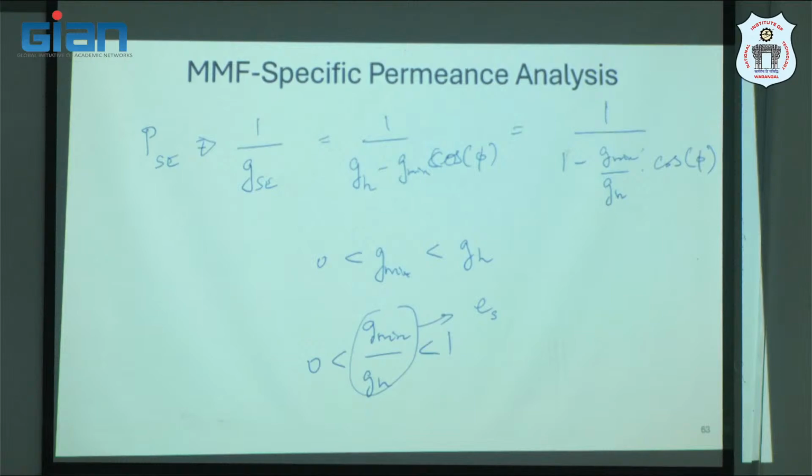When it is above 10, we are entering faulty condition and we have to diagnose it. 50% is huge, so we have to immediately stop the motor, diagnose it and fix it. Okay. So this expression becomes 1 over 1 minus severity of static eccentricity.